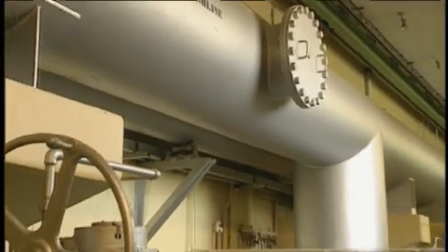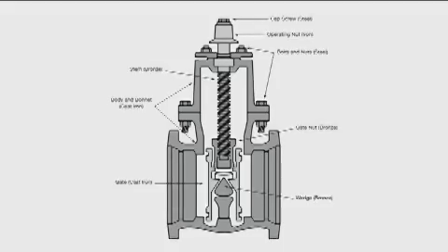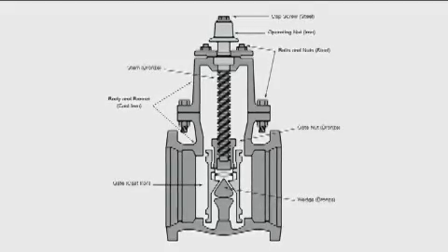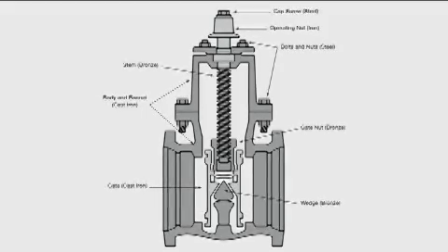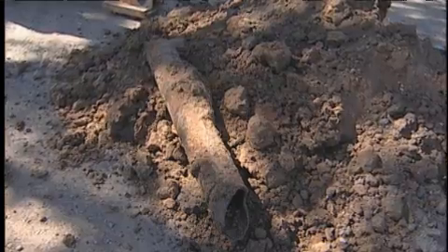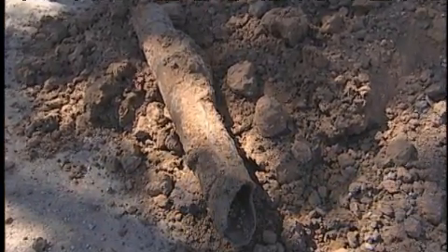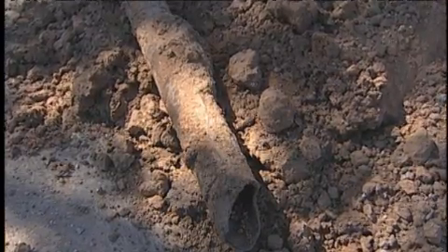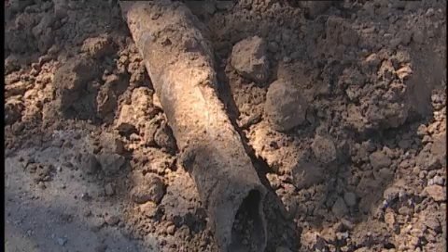Galvanic cells can easily be found in a water distribution system. For example, this valve is made of several types of metals. In the absence of a protective coating, a galvanic cell can develop and corrosion will occur at the anode. Pipes can also form galvanic cells. Surrounding soil containing water forms the electrolyte. Variances in the soil or pipe composition can create electric flow and corrosion at the anode.